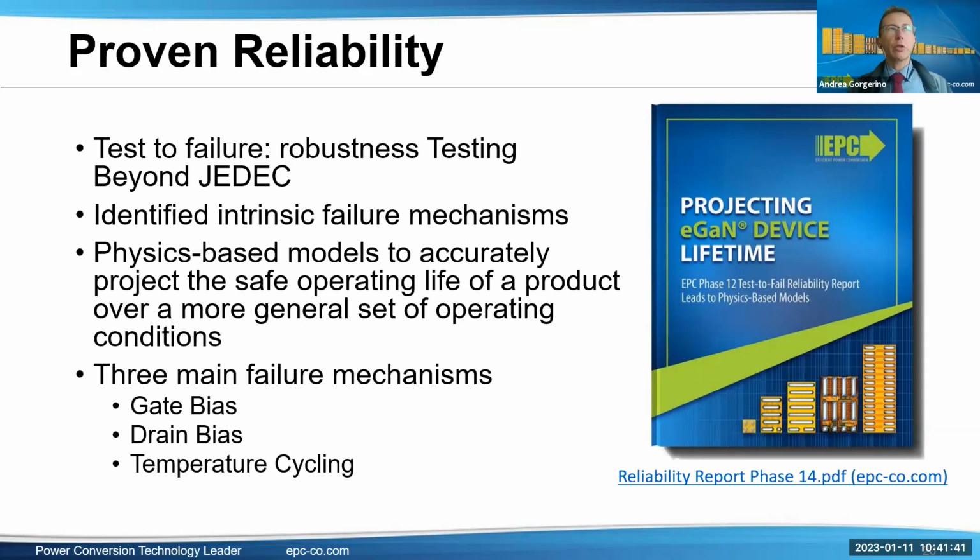And our customers have found that they were able to address the typical EMI requirements with very similar methods as the ones used to get silicon designs to pass. In some cases, there can be advantages of using GaN FETs, like the fact that there is no reverse recovery, which is a very large contributor to EMI noise that is not present here.